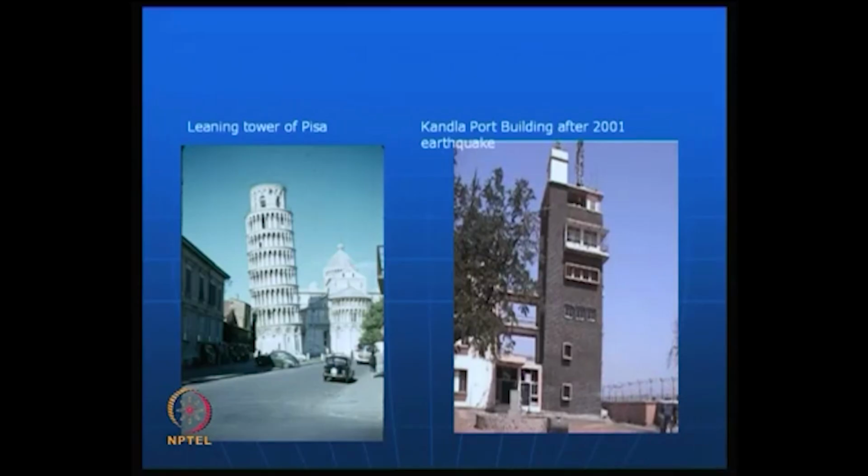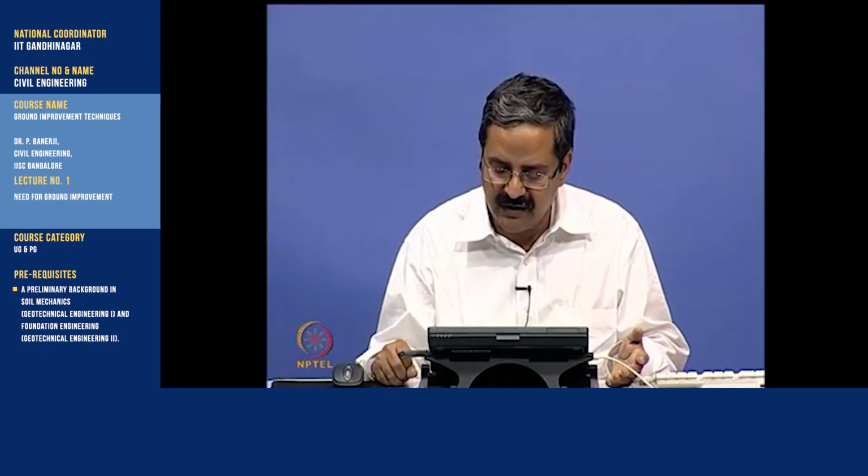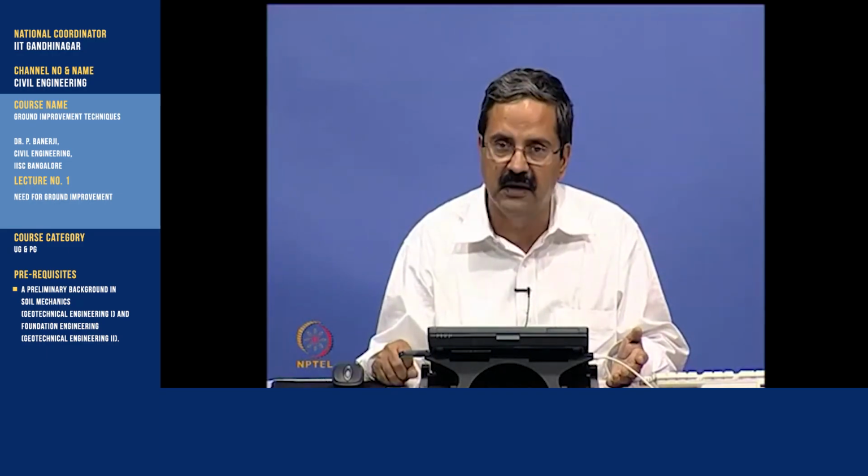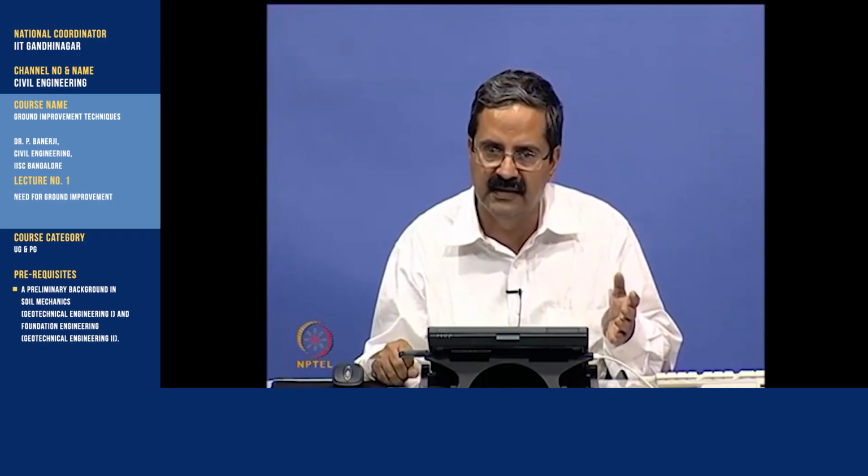So, you can see that because of this you have a tilted structure in India, but then one needs to understand the phenomenon of liquefaction and how to stabilize it to see that the structure is back to its position, whether it is an acceptable tilt or near vertical, so that this structure satisfies its function properly. So, understanding liquefaction and the effect of ground improvement techniques in trying to stabilize the foundations is another important component of ground improvement.